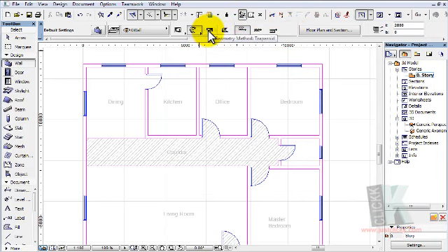You also have a trapezoid geometry type of wall, and here you have the alignment. I call this alignment but ArchiCAD calls it a construction method, but I call it alignment because it positions your wall on the existing grid you're using. So this floor plan now is serving me as a grid for the design of the 3D model.